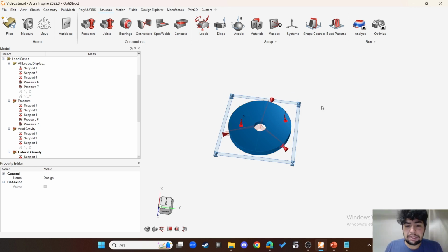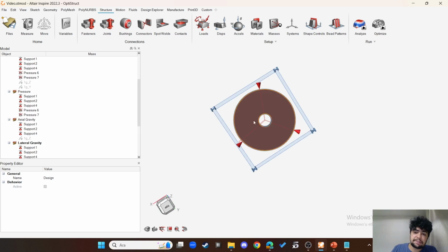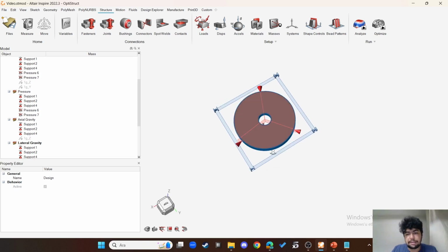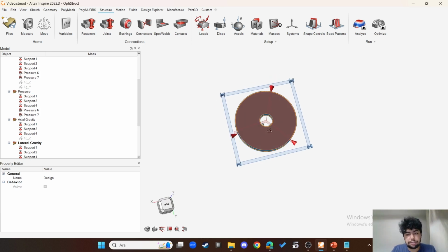Other than these load cases that you can see here, I also implemented an extrusion constraint because we produce the lightweighting structures here by a CNC milling machine, and we want our result to be producible at the end. So an extrusion constraint will guarantee that. Moreover, there is a certain symmetric condition here because I want these three slices of the mirror to be exactly the same. I use the cyclic symmetry condition.